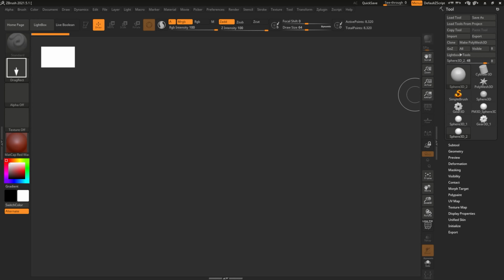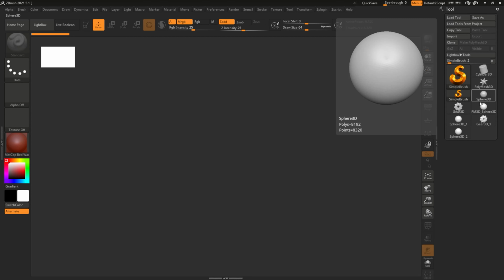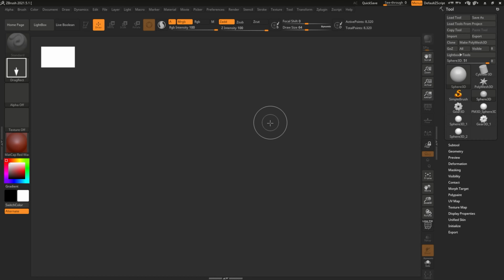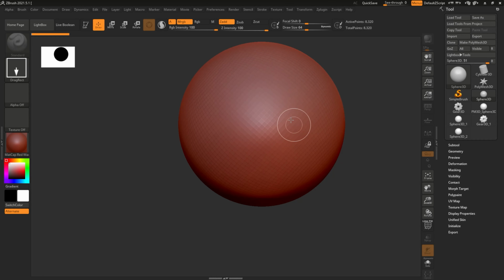This time, we will learn about importing primitive shapes together. Let's import a primitive, which are basic shapes. Let's click on the SimpleBrush function on the right tool panel. If you click like this, you will click on shapes such as Sphere 3D, Cylinder 3D, and Cube 3D below. Click like this and drag on the canvas to place it like this. At the top, click here. You must press the button to switch to edit mode. In this state, editing is not possible yet.